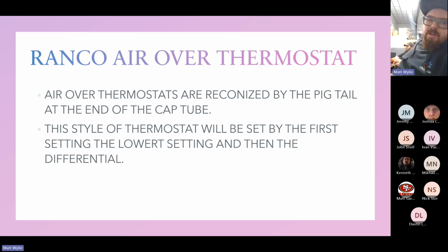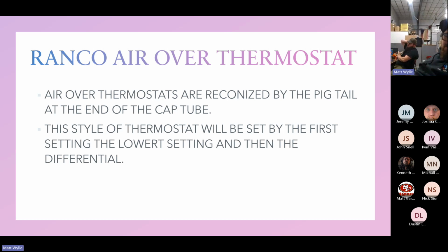Ranco air-over thermostat. That's the one that has a little pigtail coiled up on top. This style thermostat will be set by the first setting, the lowest setting, and then the differential.